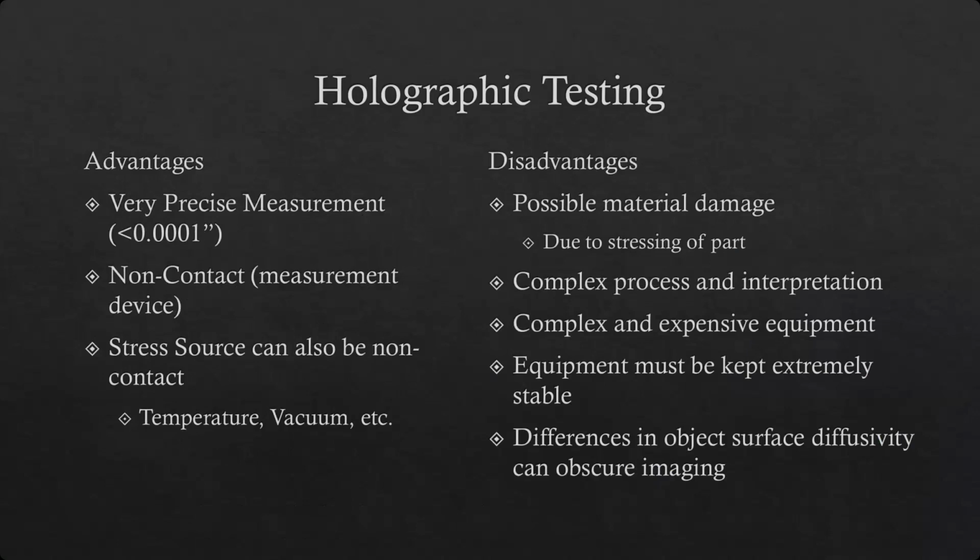The other thing about it is it's very sensitive to motion. You're measuring to the 10,000th of an inch using optics. Any little tiny movement is going to throw that off. So motion, vibrations, and that kind of thing. And then the other part is thermography. We learned about diffusivity. If you have different diffusivity areas that will absorb and emit the light differently, the laser in different areas, there may be limitations on what you can image, especially if it has different surface treatments across the part.